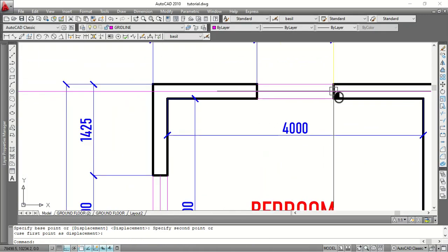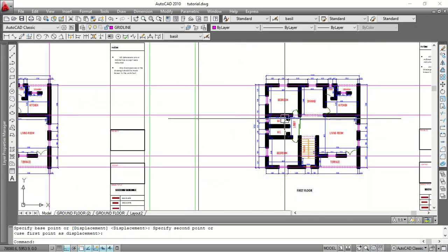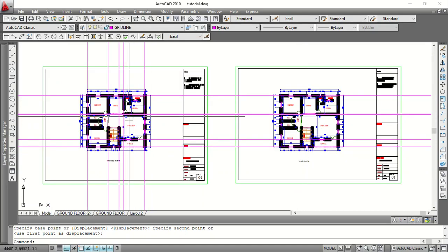A lot of people have issues in paneling because the columns from your ground floor have issues flowing through the first floor, based on the configuration of the next floor. Let's say I'm designing for two floors with different room configuration. I have to be very careful with the way I'm placing my columns, my beams and the rest of it, especially columns. Columns are very important.